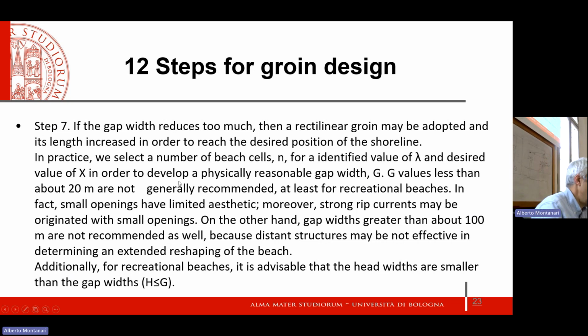One thing that I want to say, if you put the groins too close, you also run the risk of generating rip currents. Rip currents, we discussed them a little bit. They are extremely dangerous because they are currents that have the capacity of bringing swimmers offshore. Of course, this risk is particularly relevant when you get hydrodynamic of waves that is particularly energetic. If you are in a beach that is not very energetic, then the rip currents usually are not generated.